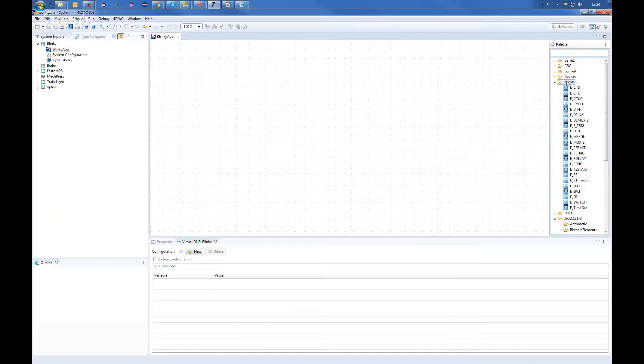The event function blocks are normally used to manage event flows through your application. But with them, you can also do quite cool things. So small control tasks can be done directly with them. For example, for our Blinky, we have a function block called eCycle, which delivers, with a given cycle time, let's say every second, an output event after it has been started once.